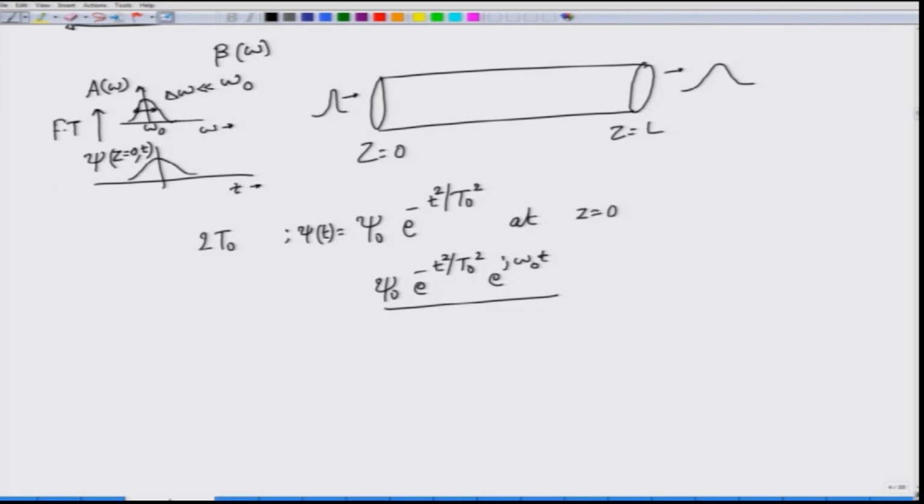But in addition to this, there is also a transverse distribution of the pulse itself. That is f of x y, or equivalently f of r phi, which tells you how the mode is distributed in the transverse plane. We solved an equation for how the mode would be distributed in the transverse plane. The fundamental mode in terms of r and phi depends like J0 of u r e to the power j nu phi, or rather for the fundamental case this will be independent of the azimuthal number phi, but this is the transverse field distribution.